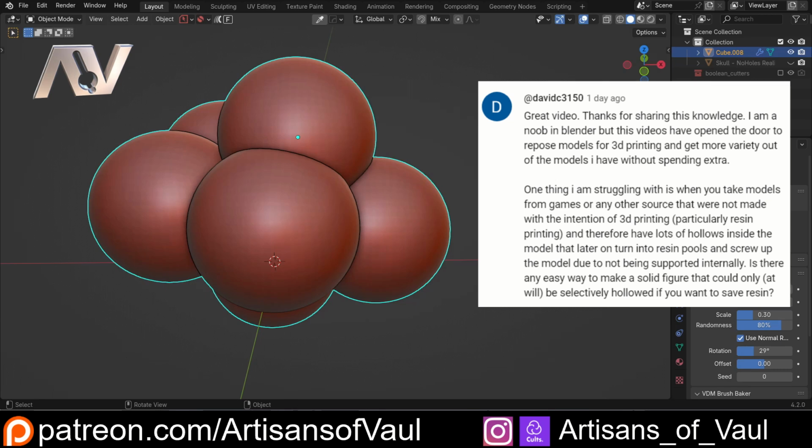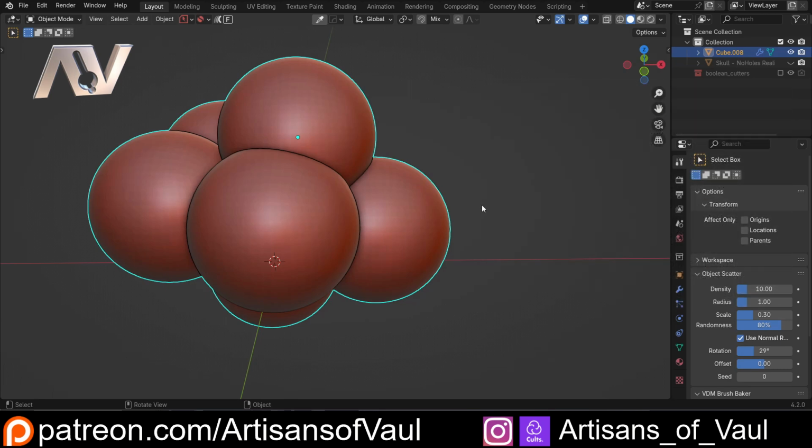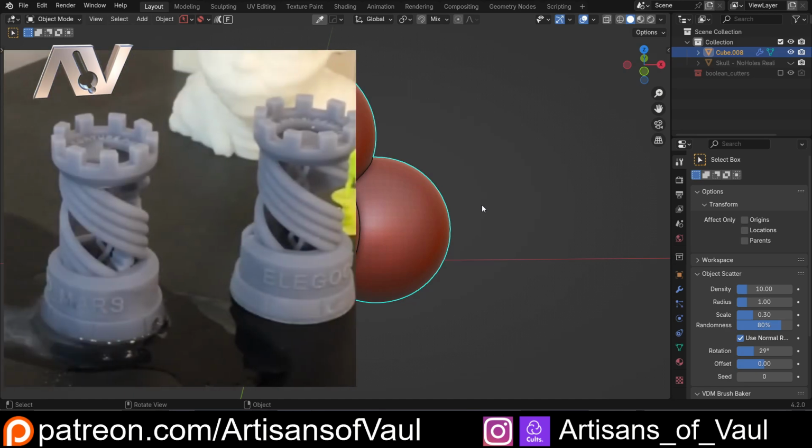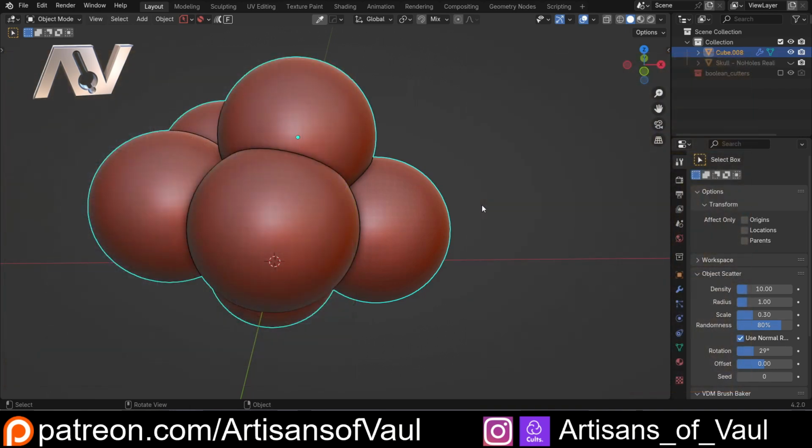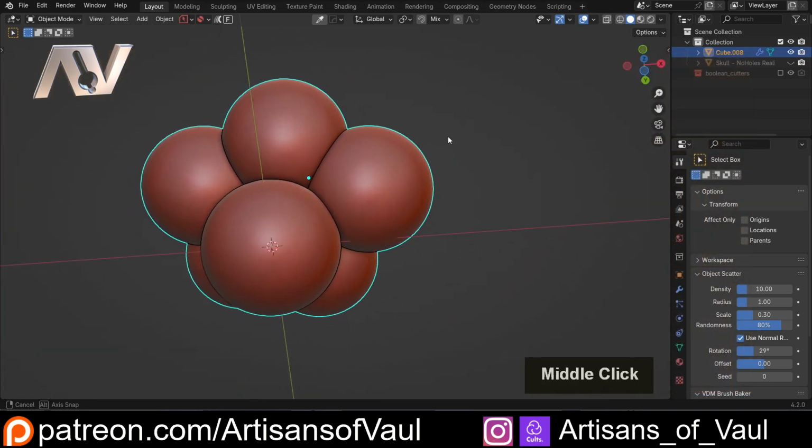It seems relatively small and unimportant, but for 3D printing, internal spaces in a model are potentially disastrous. It will lead to the resin eventually corroding the internal parts of the 3D print, and eventually that resin is going to get out and leak everywhere, and if it's for a miniature, totally destroy your paint job. So this issue can be easily created yourself by accident.